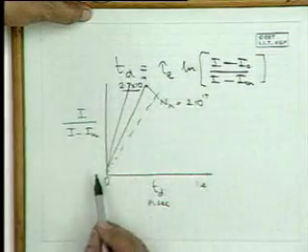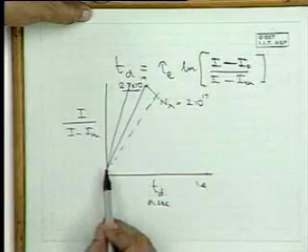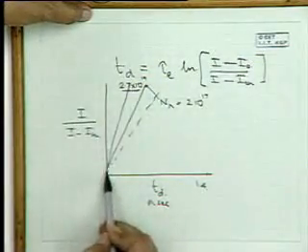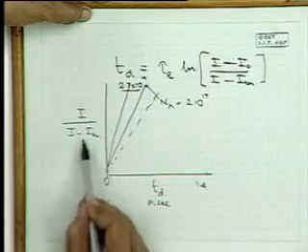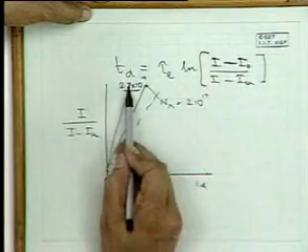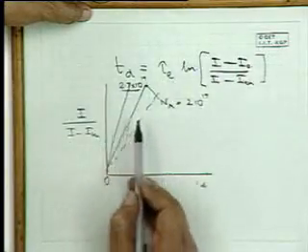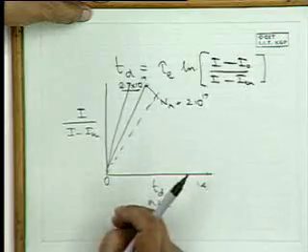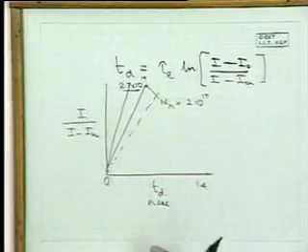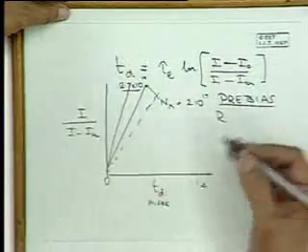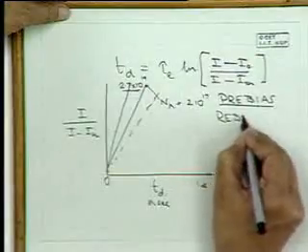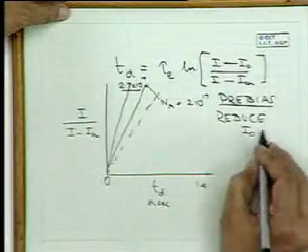Obviously, this is without pre-biasing. If the threshold current increases, then obviously the delay increases. So without pre-biasing, if we lower I_th, sure, that is the other reason. Then you have to have a different design of a laser. You can either use pre-biasing or reduce I_th. This is especially relevant when I_th was of the order of amps, or you can reduce I_th. But if it's milliamps, fine, reduce I_th.